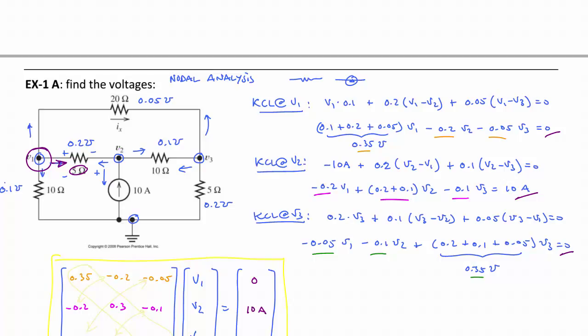But later, when I came back and did a KCL equation at node 2, I actually relabeled current going through the 5 ohm as pointing from right to left. And that was because from the reference point of each of those nodes, the current that leaves that node going through the 5 ohm resistor is in opposite directions, one relative to the other.